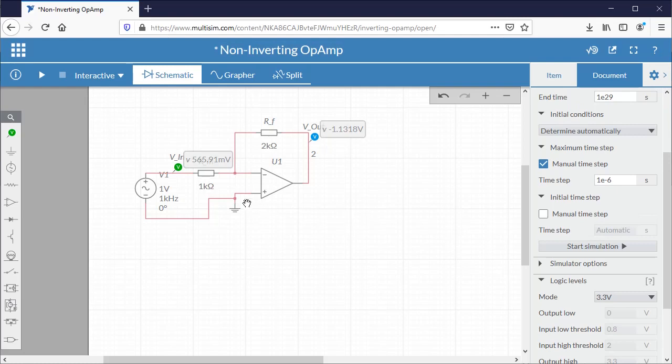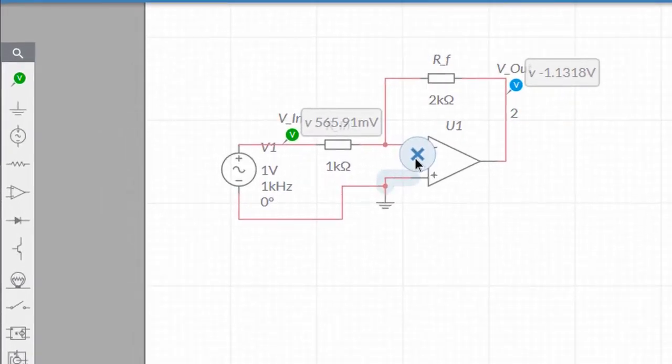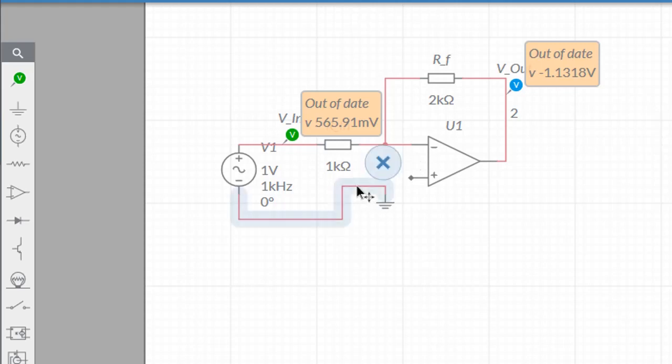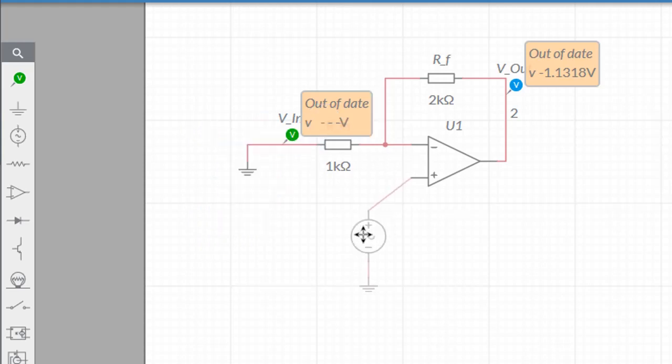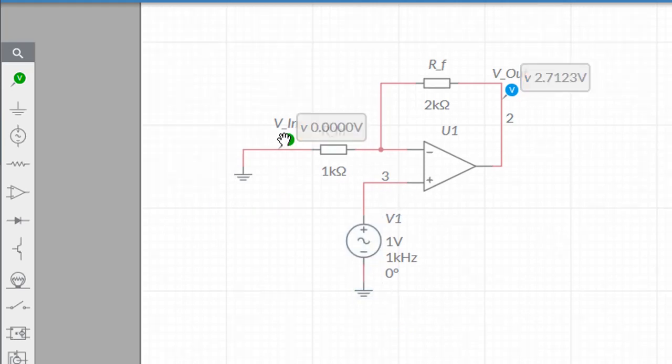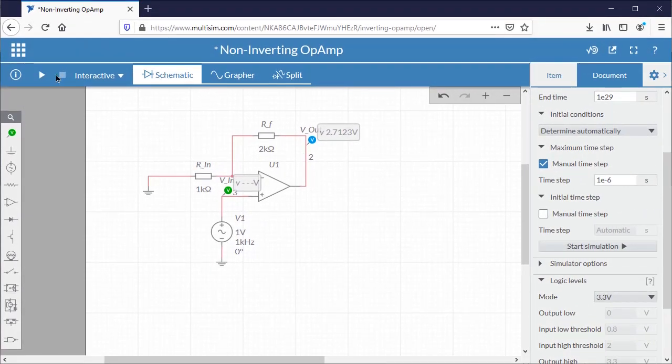Secondly, which we can use in Unit 35 devices, P4 is a non-inverting op-amp, and all we're really doing here is changing the order of the inputs. So we're going to put our sine wave into the non-inverting input of the op-amp, the one with the plus sign, and then we'll put our ground on the inverting input. Don't forget to change where you put the input voltage probe.